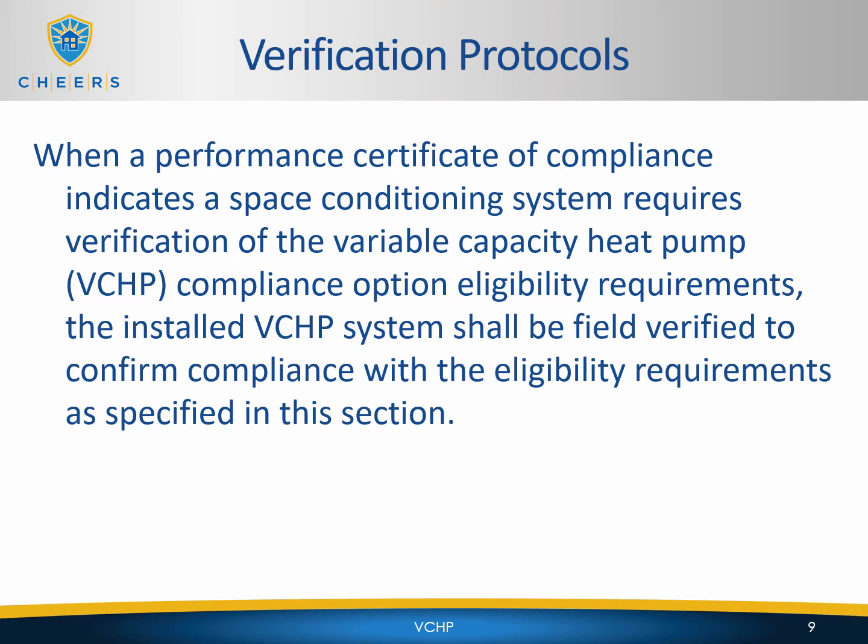When a performance certificate of compliance indicates a space conditioning system requires verification of the variable capacity heat pump compliance option eligibility requirements, the installed VCHP system shall be field verified to confirm compliance with the eligibility requirements as specified in this section. So we just talked about all of the eligibility requirements. We saw that some of them were listed as HERS verified, others were not. So now we're going to go through those verification protocols for the HERS verified options.